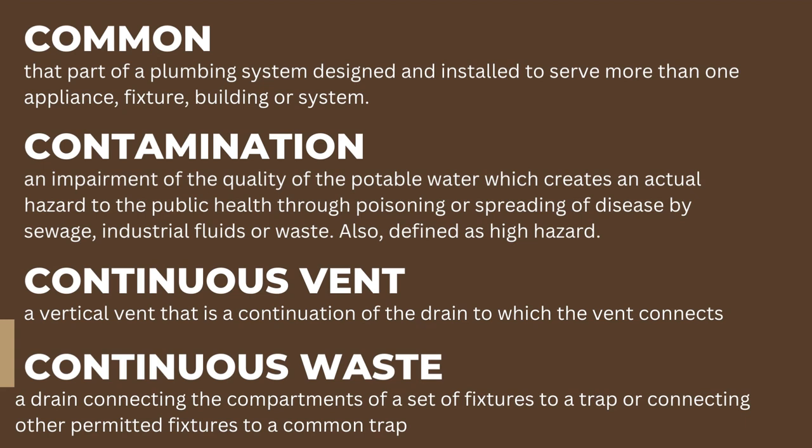Contamination: an impairment of the quality of the potable water which creates an actual hazard to the public health through poisoning or spreading of disease by sewage, industrial fluids, or waste. Also defined as high hazard. Continuous vent: a vertical vent that is a continuation of the drain to which the vent connects. Continuous waste: a drain connecting the compartments of a set of fixtures to a trap or connecting other permitted fixtures to a common trap.